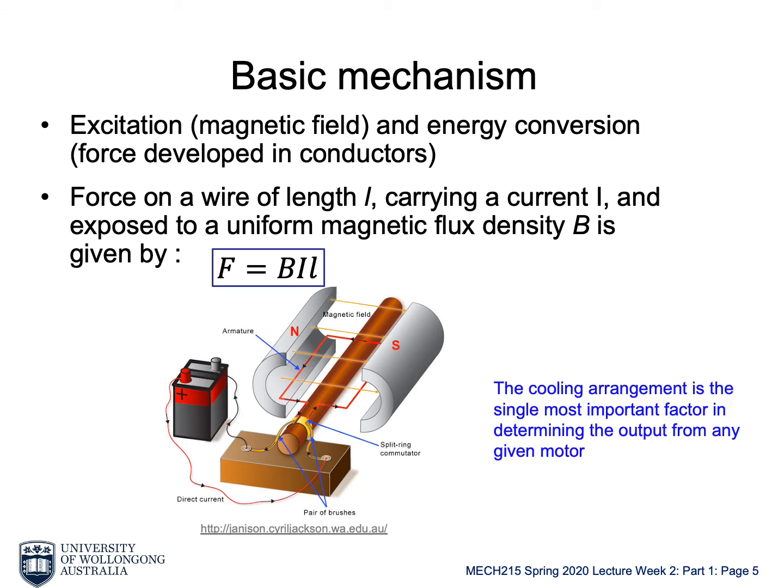The cooling condition is critical for motor design, and it determines how much power a particular motor can generate. Because we can increase the current going through the coil to generate more power, as long as there's enough cooling to dissipate the heat generated in the process. If the cooling is, let's say, perfect, if we have a superconductor here with no power dissipated as heat, then basically we can have a motor generate super large power.